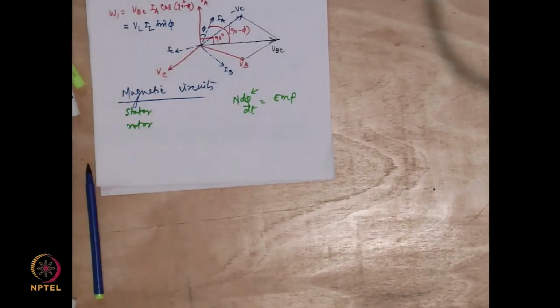But that is not going to give me mechanical to electrical energy conversion. Definitely not. I hope you understand, because I am providing electricity in the form of alternating current, and I am also reaping ultimately electricity in the form of alternating current. So I am not doing electrical to mechanical energy conversion in the transformer case.